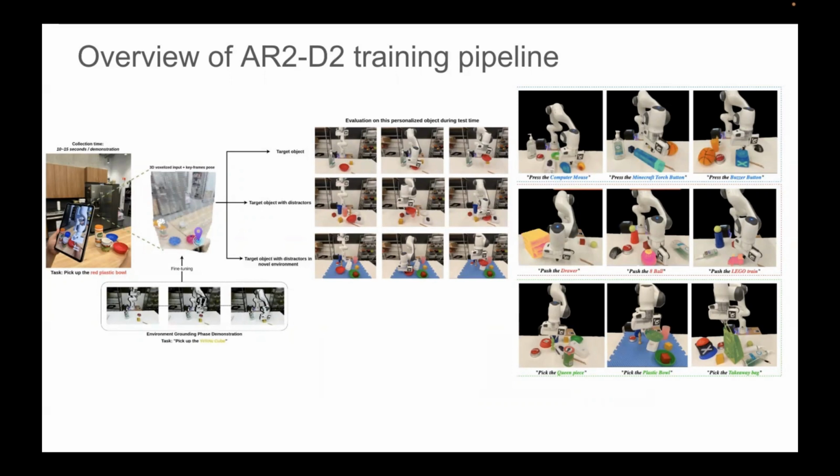We train an agent for 30K iterations per set of demonstrations. We then freeze the backbone of the Perceiver-Actor architecture and fine-tune the rest using a set of VR demonstrations on dummy objects, using HTC Vive. This fine-tuning process spans an additional 3K iterations, equivalent to approximately 10 minutes of wall clock training. Fine-tuning allows us to close the domain gap resulting from differences in depth cameras between the Kinect V2 used by Perceiver-Actor and the iPhone, iPad depth camera used by AR2-D2.